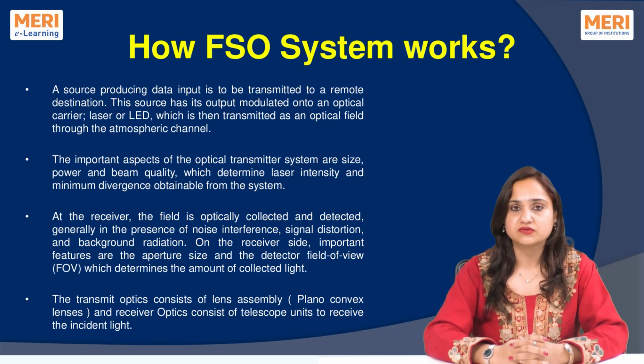The performance of the transmitter depends on several important parameters such as size, output power, laser intensity, beam quality, and beam divergence. Beam divergence refers to how much the beam spreads as it propagates through space. Lower divergence ensures that more optical power reaches the receiver.